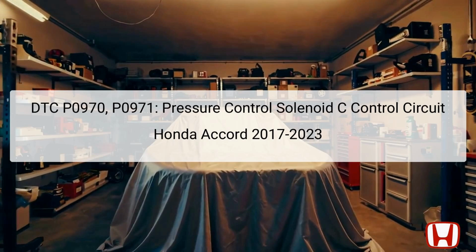Today, we will delve into the Diagnostic Trouble Codes, DTC, P0970 and P0971, specifically related to the pressure control solenoid C in Honda Accord models from 2017 to 2023. These codes signify issues within the control circuit of the pressure control solenoid, which is crucial for the operation of the continuously variable transmission, CVT.